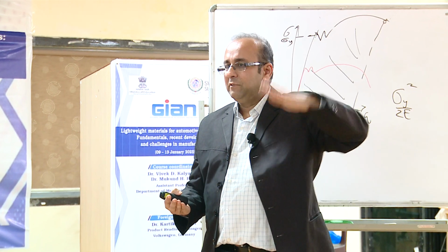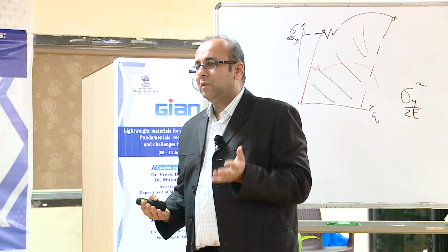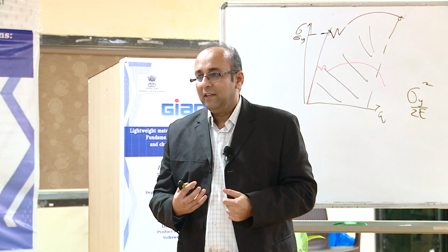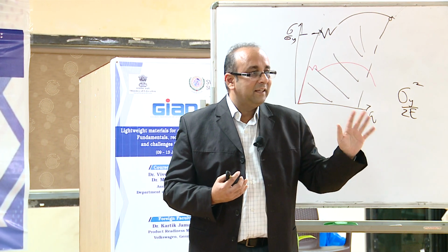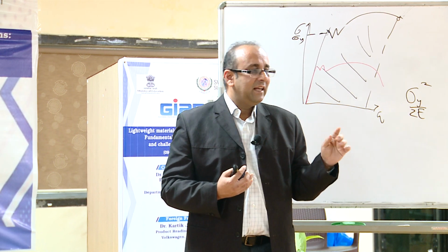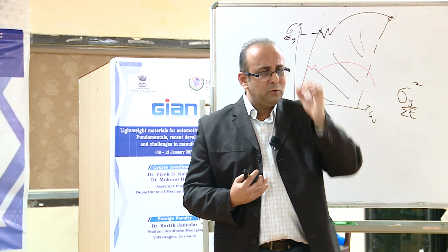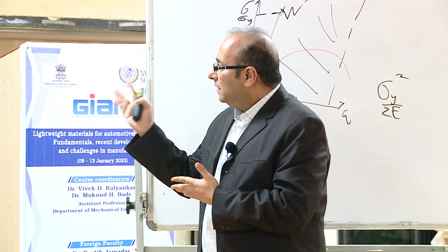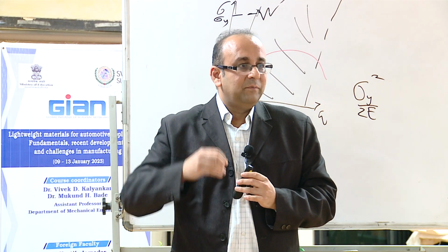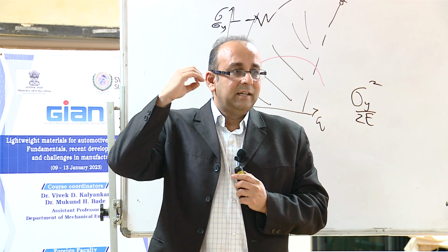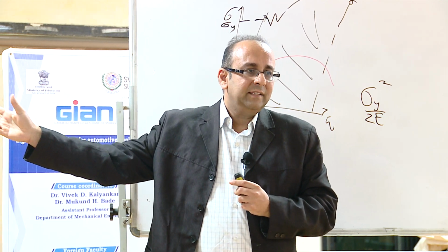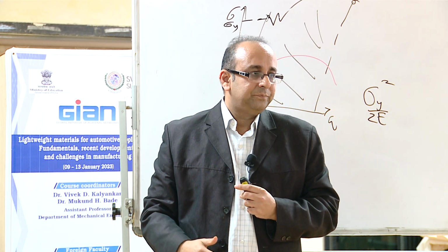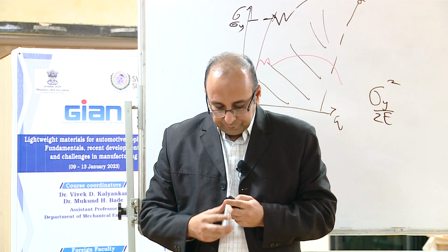The normal strokes which you see in automobile are 25 to 30 strokes per minute. That is the productivity you need. If you don't get that productivity, nothing is interesting. Everything comes down to that productivity, that cost. Mass production to the highest extent. But we have no other option because we have to increase the strength, increase the absorption. We have to give 12 seconds. It means there are a lot of machines in parallel which are doing it to get that part.